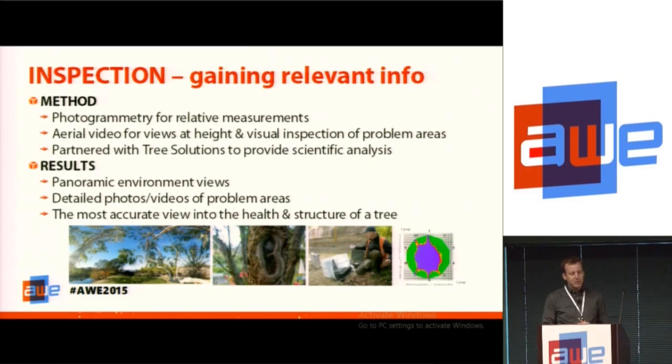The next stage, inspection, is pretty critical. This is where the accuracy of the scan comes into play, where we take very accurate point-to-point measurements, circumference and diameter measurements of the trees. Just recently we've been able to verify that the difference between physically measuring something in the field with a tape or a laser and the photogrammetry scan can be within half an inch, which within the limits of this construction is very accurate and very suitable.